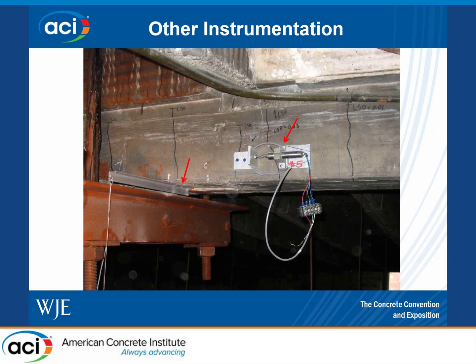You can look at considering other instrumentation during the test also. At the center of this photo, this is a beam that we're testing, and you could see an LVDT installed across a crack that we wanted to monitor during the test. I think this is a key component of the testing protocol that we typically put together. You can monitor the cracks visually with crack gauges and making notes and mapping the cracks on the girder, but it's nice to have a direct reading of the crack width during the test without having to go up to the beam, and you can pick up on any changes in real time.